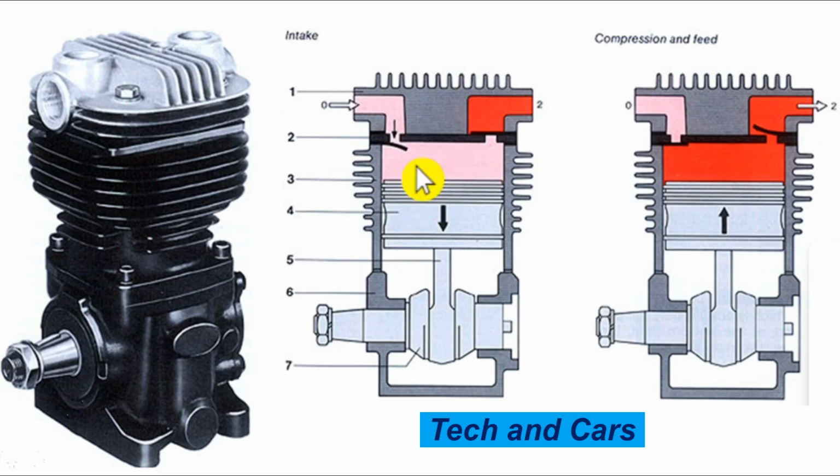There are some cases where the compressor overpressurizes. This is when it is continuously running. If the compressor runs without stopping or without any cutout, then that is also a sign of trouble. Once the pneumatic system is filled up, it has to cut out. If that is not the case, that is an indication of trouble as well. A continuously operating compressor, continuously pumping, could indicate a problem with an unloader mechanism. If the unloader valve is stuck, for example, if it is stuck in the load position, not releasing pressure from the compressor head, that can cause the compressor to continuously pump and overcompress.